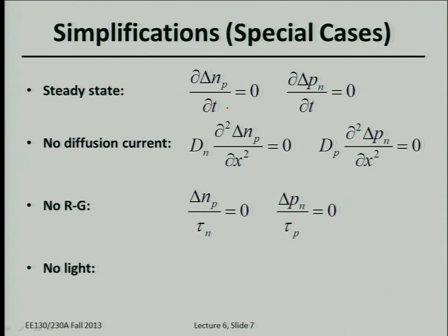That's right. You collect them. So basically, in reality, you apply an electric field. Once an electron hole pair is generated, you have an electric field. The electron wants to go this way, the hole goes that way. They never see each other again. They never have a chance to recombine. That's right. So that's what happens at a junction, like a p-n junction.